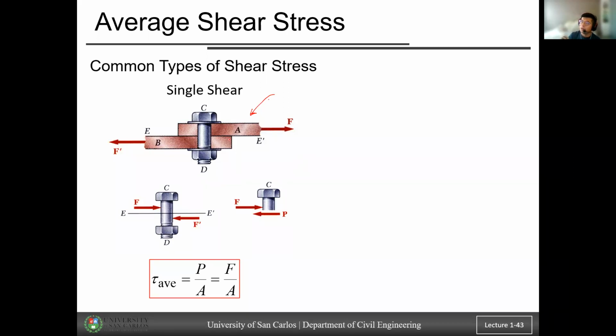If you are looking for the failure part, most likely the material that will fail is this bolt. And you can imagine the area by imagining where the material will fail. Again, as per formula, shear stress tau is equal to V over A.